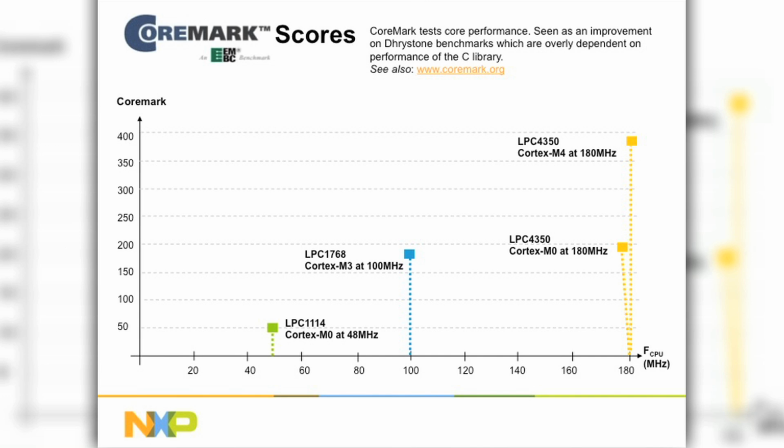So what CoreMark tends to be used for, let me take a step back. If everybody with an M3 or an M4 core runs CoreMark from internal memory, it should be the same amount, 0 wait state. The score should be identical because it's really a measure of the core performance. It has nothing to do with the peripherals or the I/O. Assuming you have 0 wait state internal SRAM, the score should be identical. And what you tend to see is CoreMark per megahertz. And typically, you'll see 2.1 range for the high performance M3s and M4s. Then, of course, this is CoreMark measured times megahertz. So again, it's a performance of the clock speed.